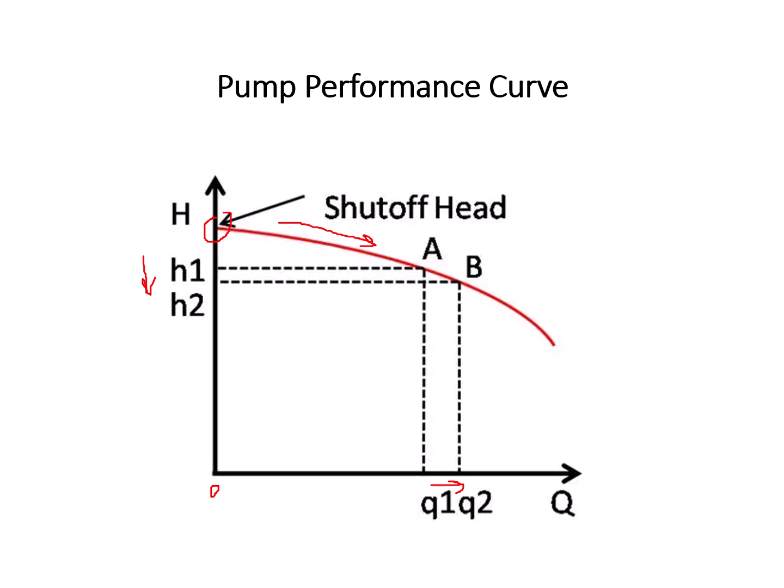Don't be afraid, it's not dangerous if you are applying a centrifugal pump and you shut off the valve. But if you are using a reciprocating pump, we will discuss this later on, you have to be very careful, and there should be some relief valve to prevent excessive pressure buildup.